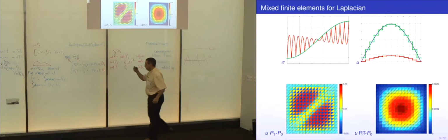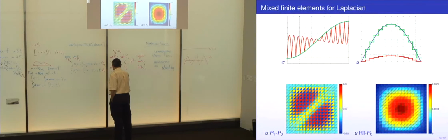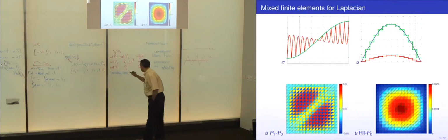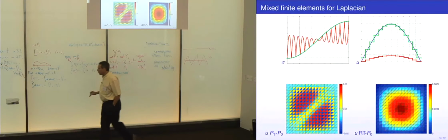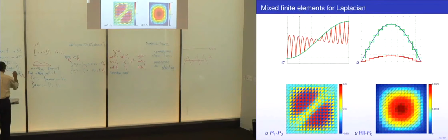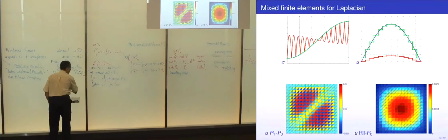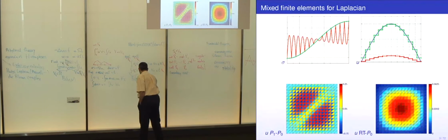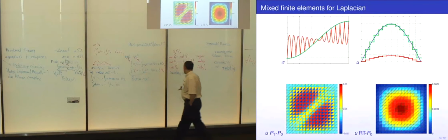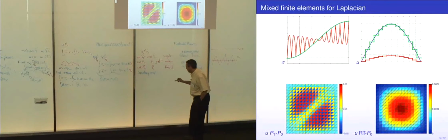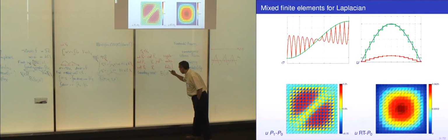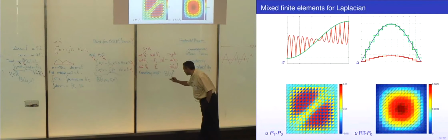Well, for finite elements, for Galerkin methods, consistency is measured by having a small consistency error. And that would be if you take your bilinear form. So here our bilinear form, B of u, v is this. And here our bilinear form, B of sigma, u, tau, v is this. The consistency error is: you take B, you put in a known good approximation of u, like the interpolant or the best approximation or something like that, in the subspace.